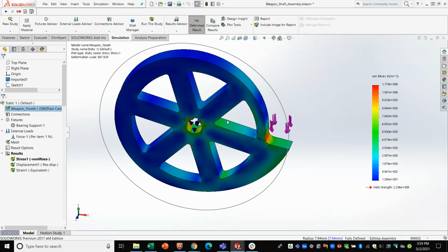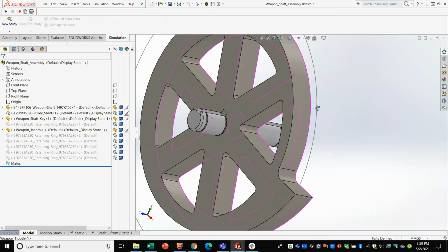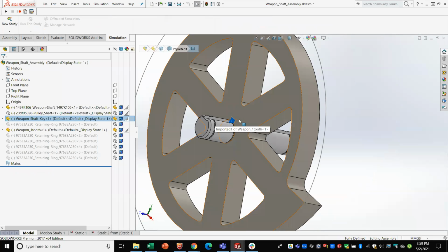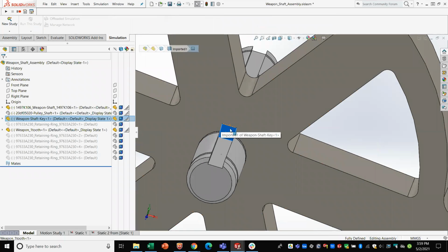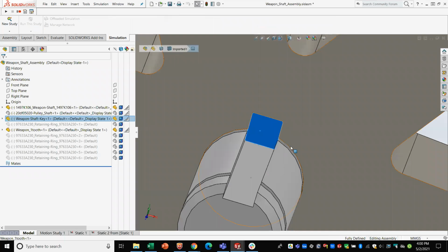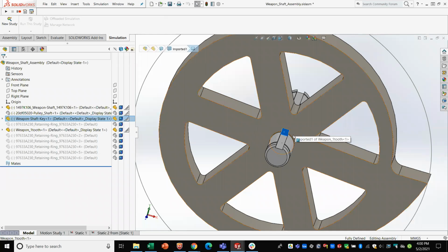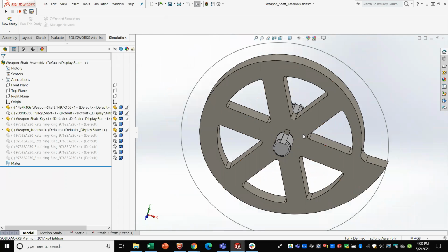So as far as design feedback goes, coupling FEA with experience, one thing about keyways is that the keys are not designed to be made out of hard metal. They're designed to be made out of soft metal. The point of the key is that the key should shear, into a semicircle, before the rest of the system fails, and thus allow the disc to free spin around the shaft when the key fails.